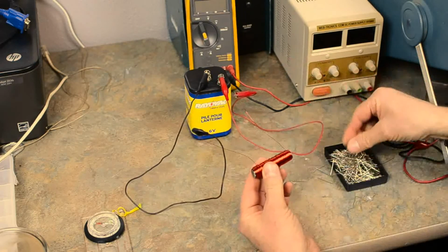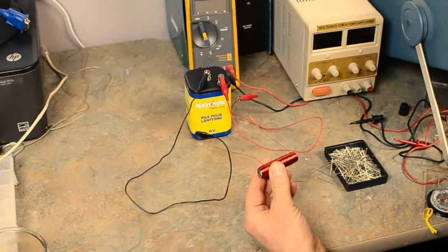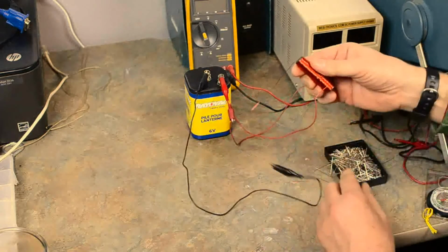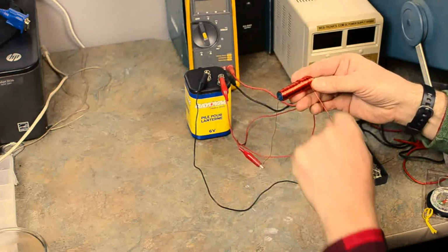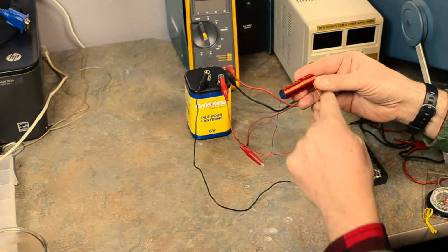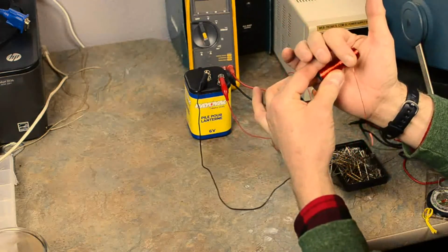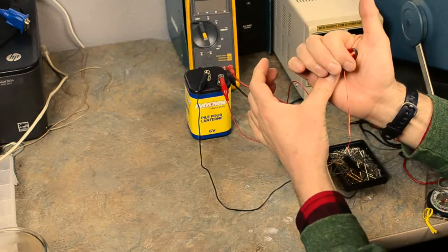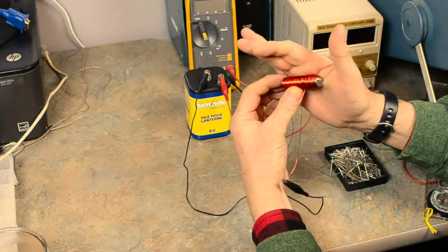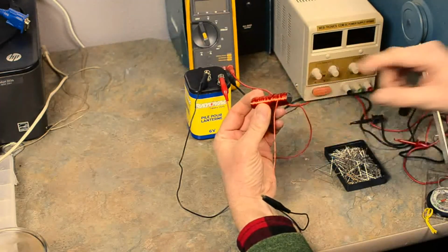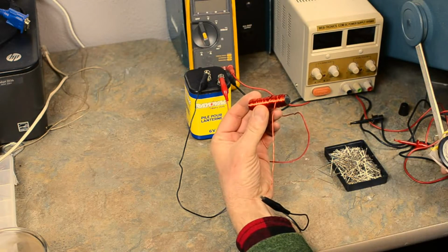And I am going to, let's do a pole test here. So before we do a pole test, let's predict what it's going to be, okay? So I have current flowing in this direction, okay? This is my positive lead and this is my negative lead. So I want to use my right hand rule and I want to shape my fingers in the direction that current is flowing. So that would be in this direction here, and my thumb will be pointing to the North Pole. So this should be the North Pole, which should mean what as far as the compass is?